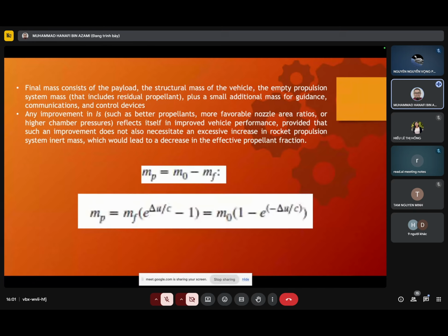That is why you see that in a rocket nozzle we don't use a conical, triangular shape, because the nozzle can be long. So that is why we use the Laval nozzle, which is a bell-like nozzle.